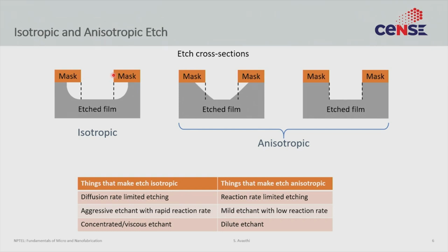This becomes problematic for etching depths that are too thick or for openings that are too small. Any time your opening becomes the same size as your etching depth, you need to start worrying about the impact that isotropic etches will have on your feature sizes. Often if you can characterize what this lateral etch is, then you can compensate for it in your design itself.